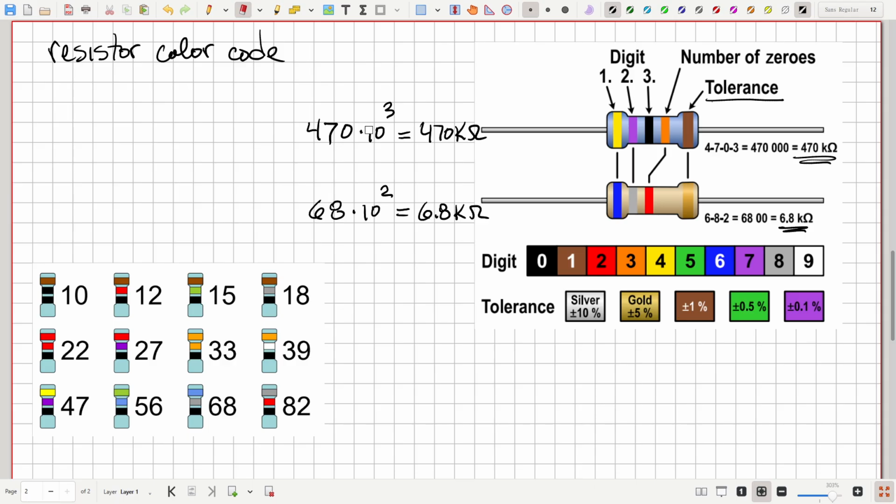So then the question is, well, since we can only manufacture a certain discrete set of resistance values, what should those values be? And you'll notice here, this goes up by 2, this goes up by 3, and then here you're going up by more than 10. So they're not equally spaced. And that's because in practice, as we'll see when we start looking at resistive circuits, resistance values typically come into play in terms of ratios.